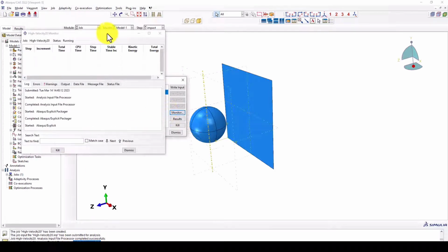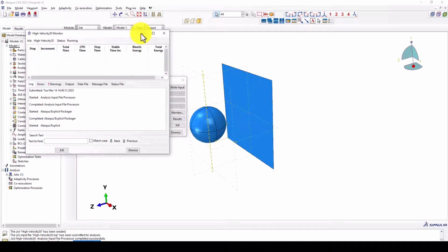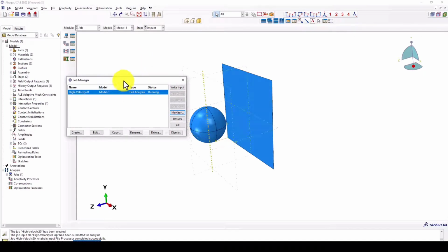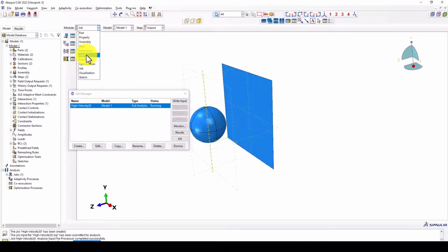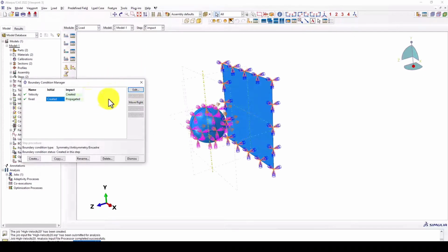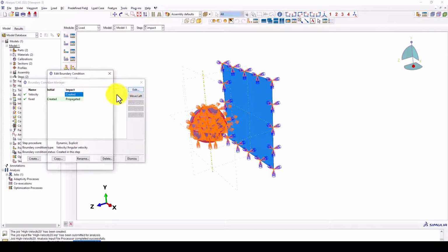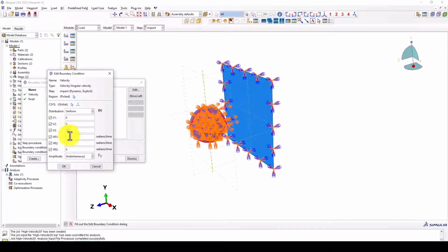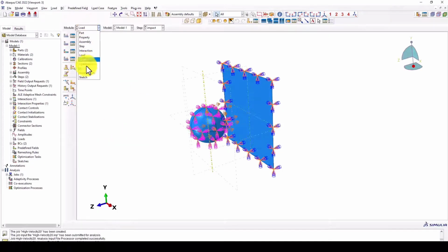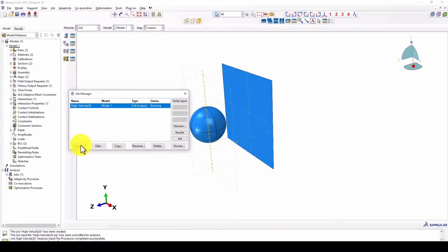If plastic deformation is expected, we should also define the appropriate plastic stress-strain behavior. For high velocity impact, material modeling can become much more sophisticated. So we need strain rate dependence, damage initiation, damage evolution, and failure, and potentially an equation of state to govern extreme impact regimes. So the material model should always be selected based on the physical problem.